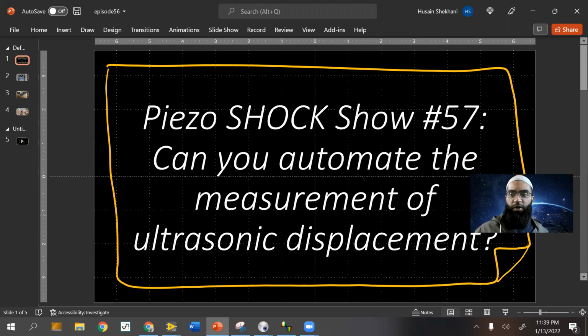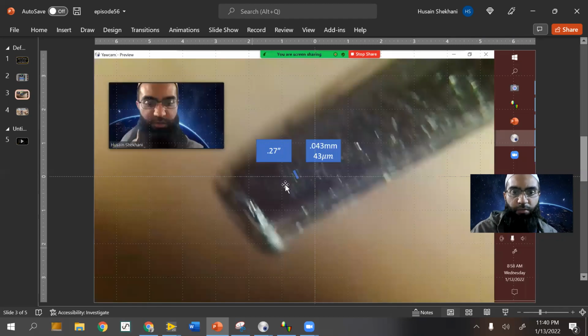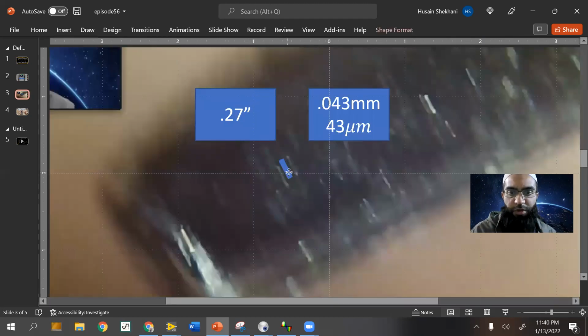But meanwhile, I just wanted to go over those concepts with you regarding the histogram, regarding how you can actually measure those displacements accurately. There are a bunch of programs that you can use to analyze this data, but the easiest way is obviously what I did here, visually counting those pixels using a draw program with the drawing tool. That's one way. There are also reticles that can be installed in stereo microscopes that can be used there. There's a couple of ways, but I just wanted to show you what I've been working on. We can automate this process.